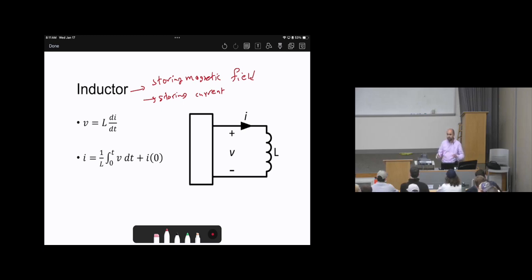For example, let's assume some power utility company wants to do maintenance on a certain transformer. When they disconnect the power, it's still unsafe to start their maintenance. Why? Even though there is no power source, there is some residual current stored inside this transformer, because the transformer's equivalent circuit is based on inductance. So there is some energy stored in it.